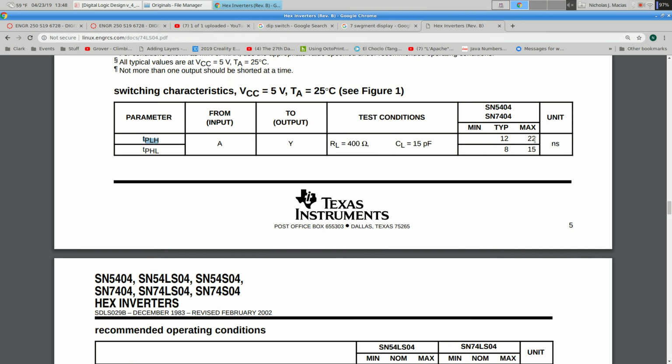And if you run the clock too fast, you're trying to do things before what you did after the last clock tick has fully caught up. And up to a point, that works fine. Beyond that, you start glitching out a little, and beyond that, things aren't doing the right operations logically anymore, and usually your CPU crashes. The bigger danger, of course, is heat. The faster you clock, the hotter things go, and that's why you have liquid nitrogen cooling your CPU or dry ice or something. And usually your CPU might overheat and sometimes actually smoke or flame before you actually get into performance problems.